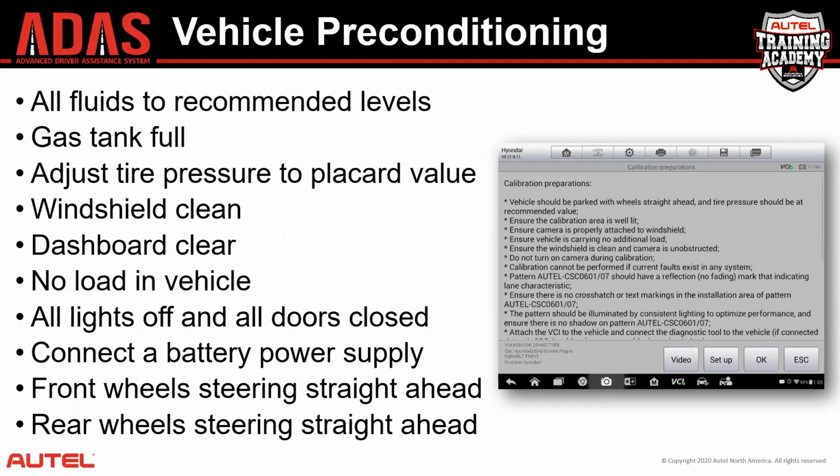Sometimes they will specifically call out the engine oil and the coolant. Make sure the gas tank is full. This is probably the most often skipped step, and it's a critical step because of what the OEM is trying to do here: putting this vehicle in a specific stance to make a calibration successful.